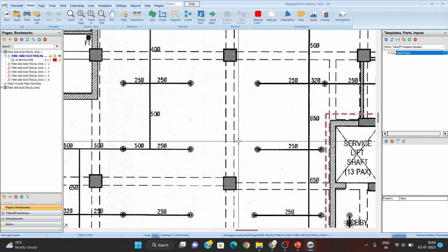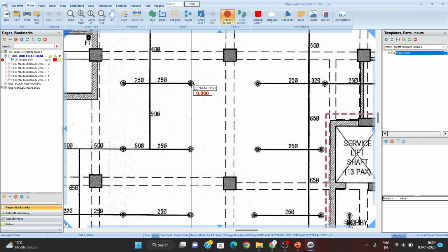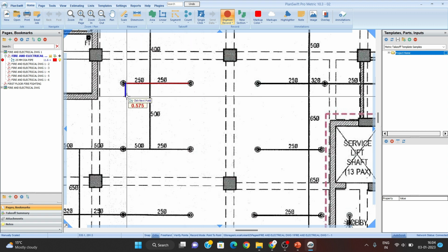Then how to work fast? How to work quickly over there: just go here, you don't need to select every time, you can just keep your cursor here and turn on your digitizer. See, I have taken 25 again, mouse left button till here. Now if we press the mouse right button and press stop, then the command exits. The command is off, the digitizer button is off.